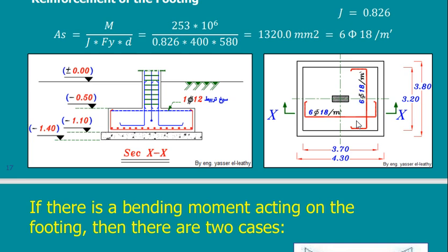If you are using a different cantilever, then you would have repeated the design twice. So this is now 6,518 here, 6,518 in the other direction. I use U-shaped rebars. I don't put top reinforcement in an isolated footing.